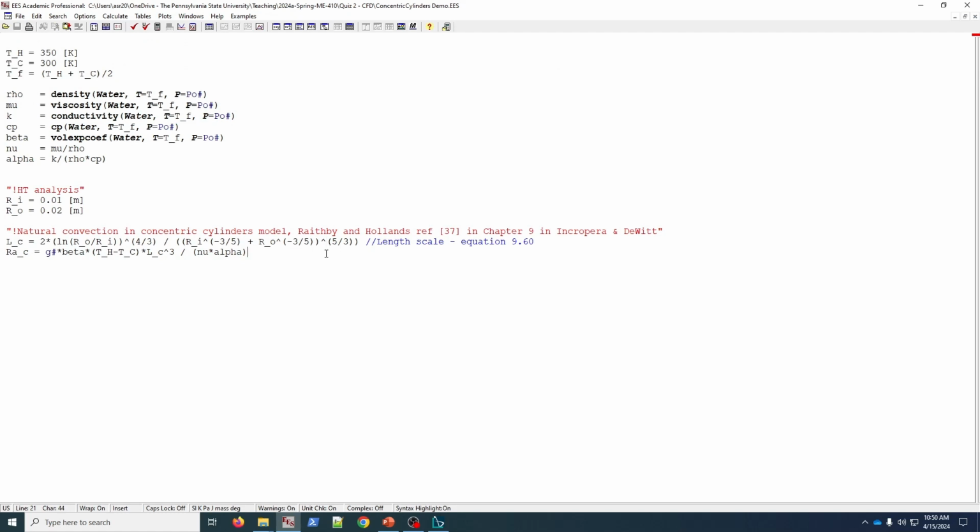Okay, now let's calculate the heat transfer correlation, and the way it's defined is based on an effective thermal conductivity. So in other words, it's defined such that the natural convection is treated as just increasing the effective thermal conductivity of the material in the gap rather than with a regular heat transfer coefficient, and that way you don't have to worry about different heat transfer coefficients whether you're using the inner or outer tube diameter.